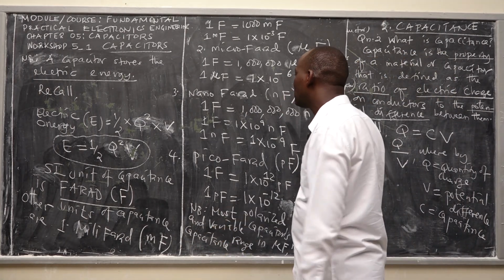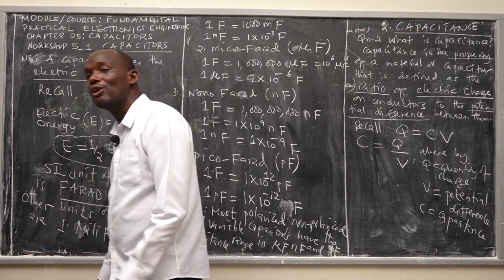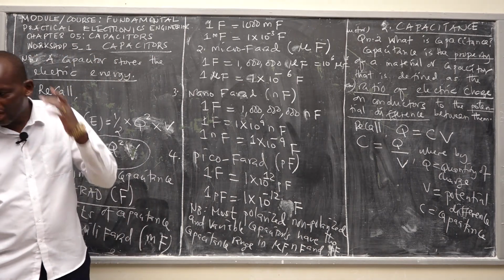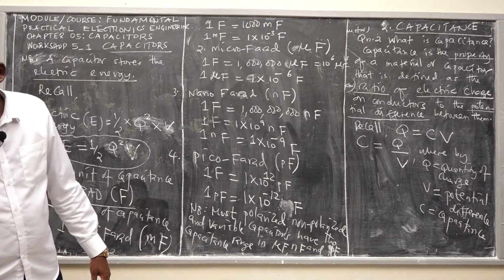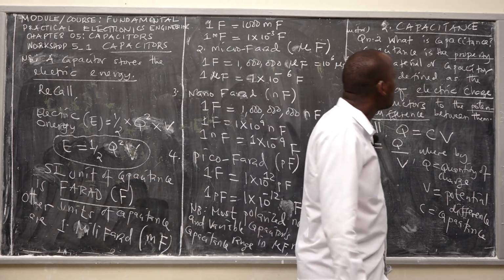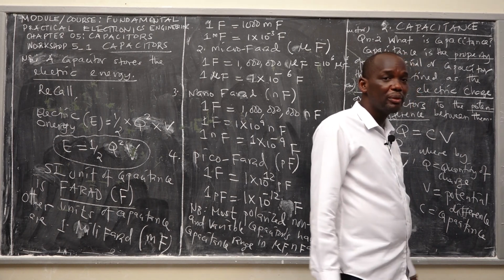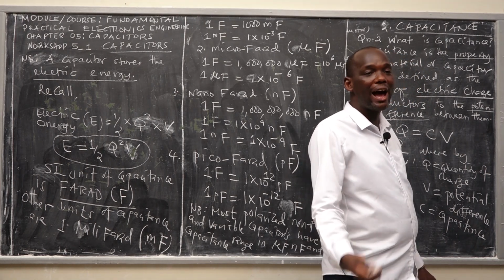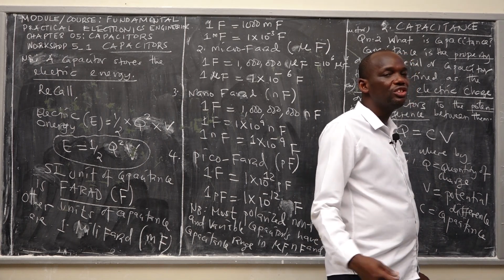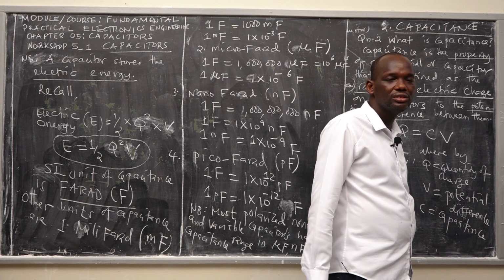What the capacitance of this capacitor? Okay, that is 2,200 microfarad. It's equal to how many picofarad? Just convert it. So you know what you have to convert in your mind. Okay, this capacitance is what? Okay, that is 1,000 picofarad. 1,000 picofarad is equal to how many nanofarad? It's 1 nanofarad. How many microfarad? It's 0.001 microfarad. That's how you have to think about it.